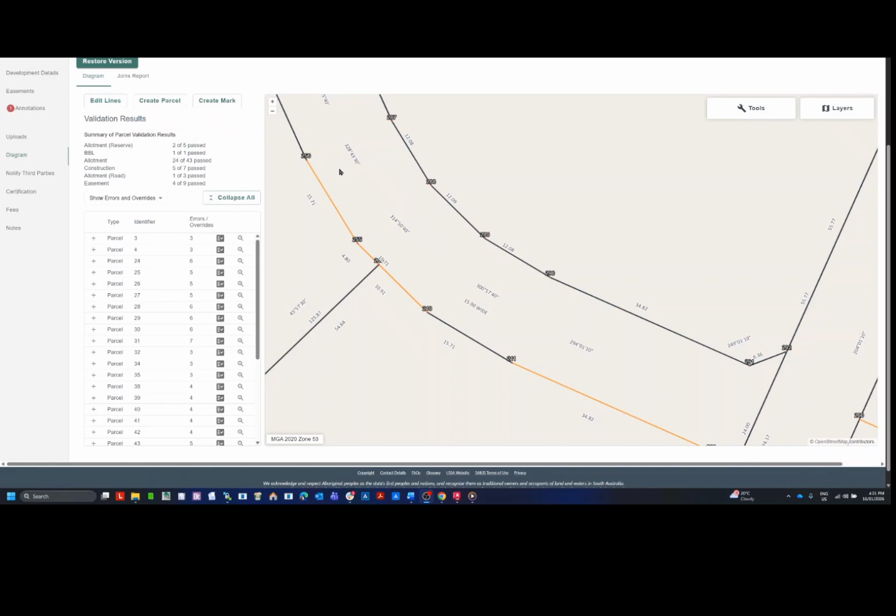here where we just have a bearing label but no road width label. And this is the same for easements where you might have easements with parallel lines. If you just provide the one bearing label in the middle of those parallel lines, we'll only be able to associate data with one line and not both. In the case where you don't have a road width label to add to it, the bearing labels will need to be provided for both sets of lines. So you'll need a bearing label for the top and a bearing label for the bottom line.